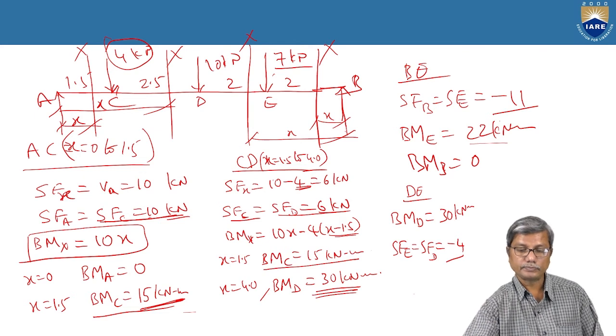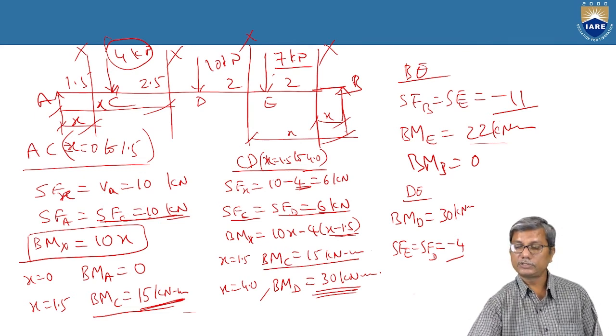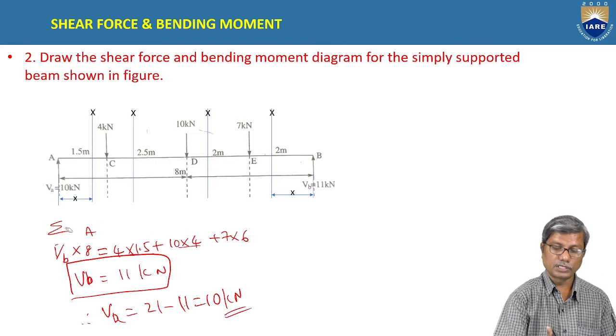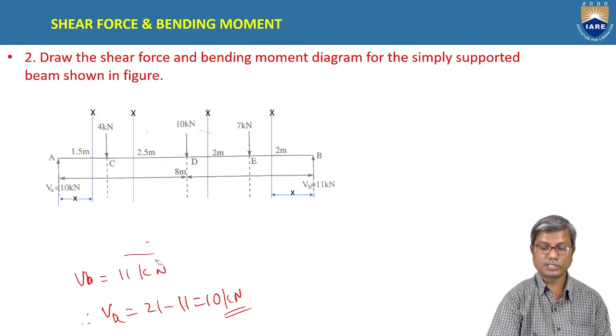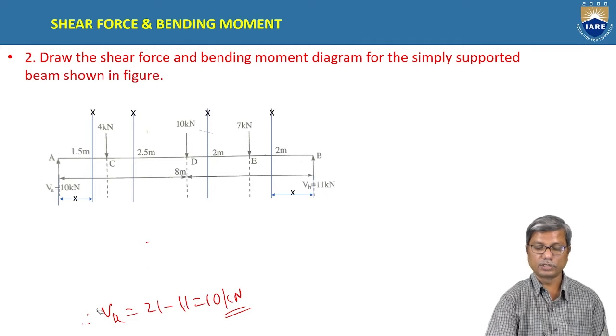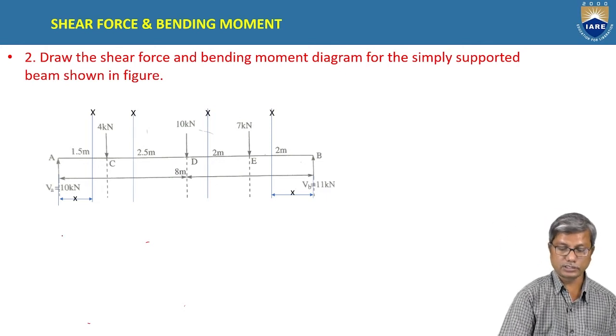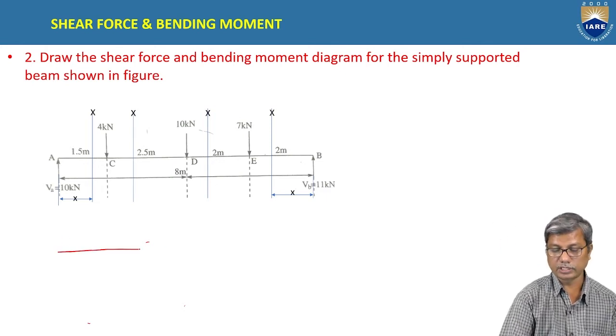Now with these values we can plot the bending moment and shear force diagrams. For that you consider this figure. In this figure the shear force diagram can directly be drawn because it involves only additions and subtractions. Without these calculations we can directly draw the shear force diagram.